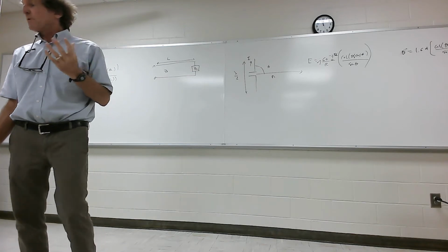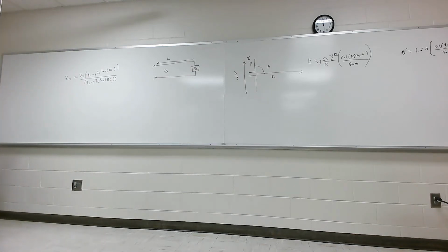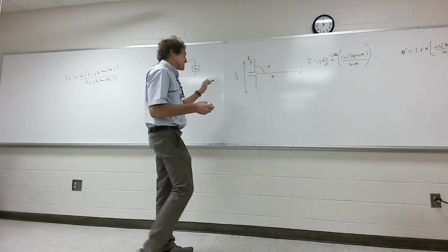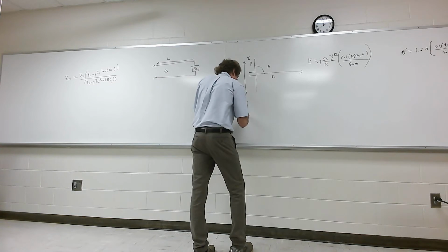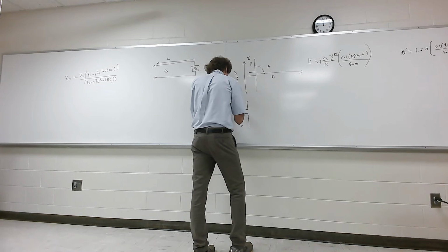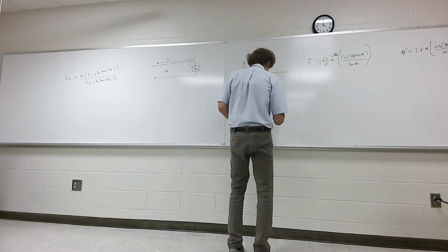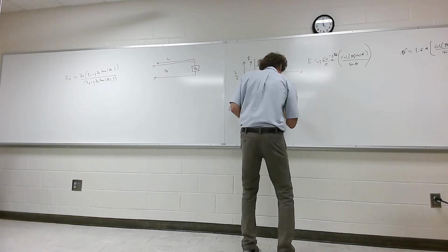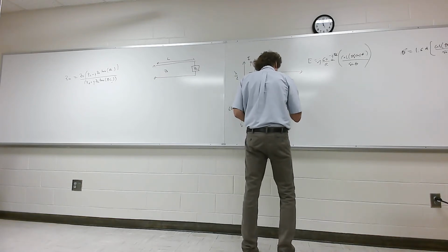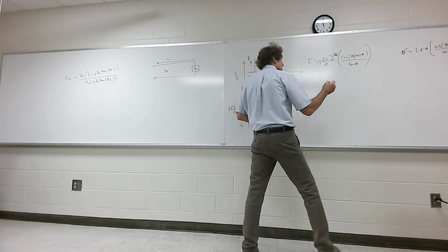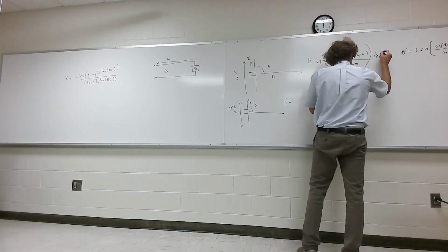But what do we know about the small loop and the short dipole? Same gain, right? The same exact gain, 1.5 times the sine squared of theta. And again, this is a half-wave dipole. If it's a short dipole, if all of a sudden L here is less than lambda over 10, and this is I naught on it, and this is the angle theta, I know that the electric field right here would be equal to, I don't put this in here, but it's the A theta direction.